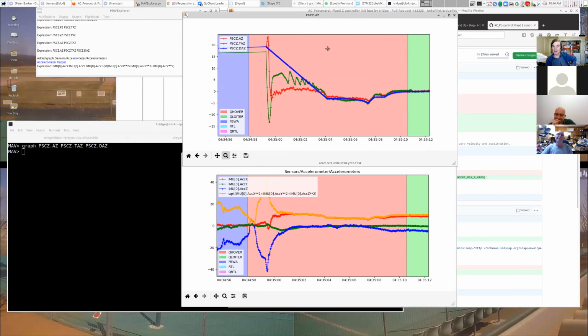Indeed. I haven't gone quite that dramatic, but I have been adjusting the parameters for this model for an auto landing, where it's coming back and doing the back transition auto landing. And I found basically this model can fly at, there is no lower end on the stall speed. It can fly in fly-by-wire mode all the way down to practically 0 speed, because it just puts the nose up and up and up, right? And it can then come in at very high pitch angles, high deck angles. So I've now set the land speed really low.